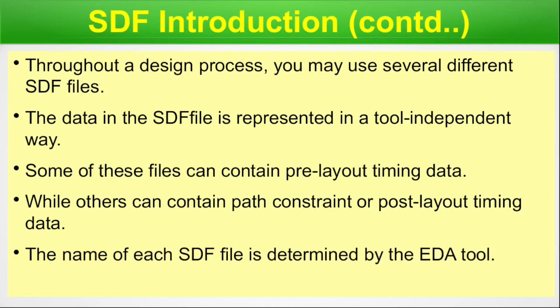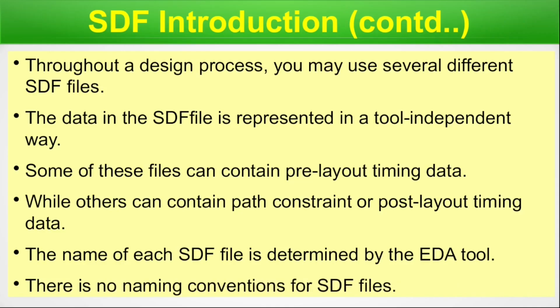The name of each SDF file is determined by the EDA tool. So each EDA tool may create the SDF file with a different name. Generally, as a rule of thumb, if you are working at the STA level, the name may contain the text STA. If it is generated by the PNR, it may contain the text PNR. The conventions differ from one company to another. There is no naming convention for SDF files. In general, there is no rule of thumb for how you name an SDF file. It may be a convention specific to a company, or you may write the name as you like or as you can identify. So we are done with the SDF introduction.